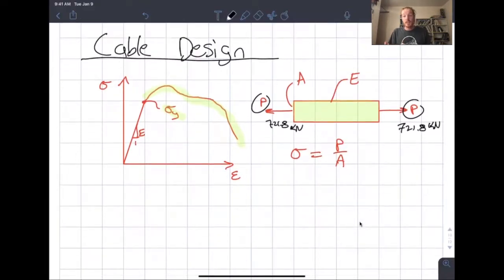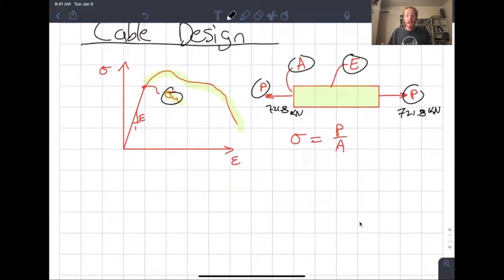But what's typically given with steel wire rope is not these properties or even the yield stress. What's given is the ultimate breaking strength. They tell us what that is for the specified cable, because the geometries change, and it's an easy quantity for cable manufacturers to test.